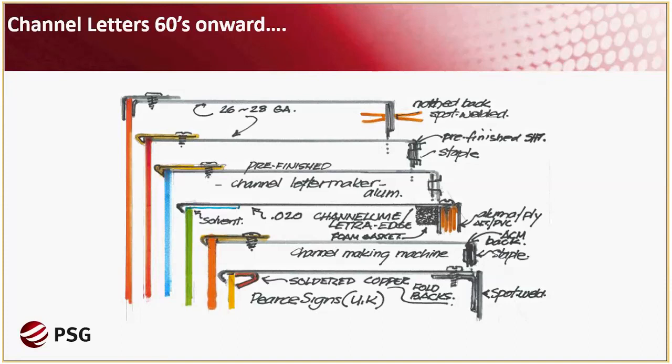I included the English method for making channel letters because it had, and it still has, a very interesting process. They would solder little copper clips that would bend back to support the plastic face, and servicing would be done from the back.